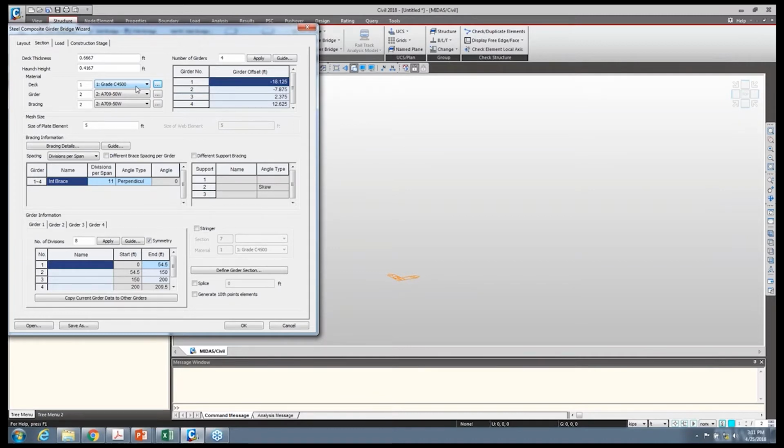The next section we get to is the section girder layout and material properties. As you see here, we're working with a deck thickness of 8 inches, and this is standard for the state of Florida. Actually, on most Florida plans, you'll see 8.5 inch deck thickness specified, but the extra half inch is an additional sacrificial width and is not part of the structure itself. The haunch height here, I've selected to be 5 inches.